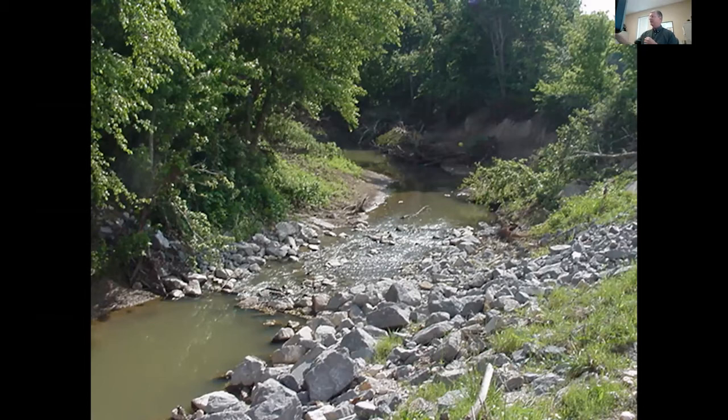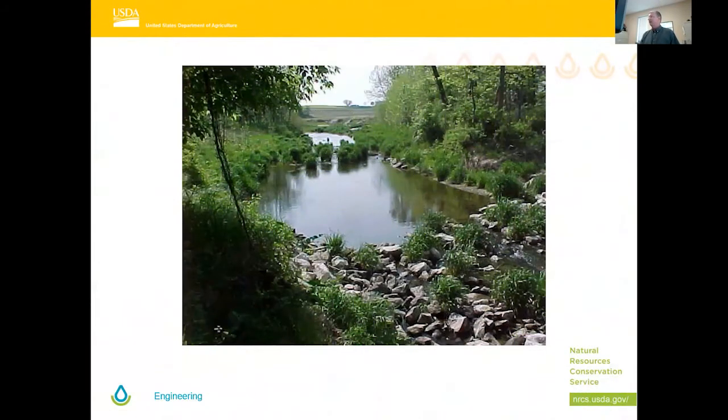Sometimes the crest of the riffle would almost back water up onto the toe of the previous one upstream. If we need that level of protection in the channel, we can engineer a system where the stream is actually at low flows backing water all the way up to the previous riffle. So this might be what it would look like over a long-term setup where you can just see the coarse stones, and they almost seem like a natural rock riffle that you'd find in a channel, only it's kind of an engineered solution to allow grade stability.